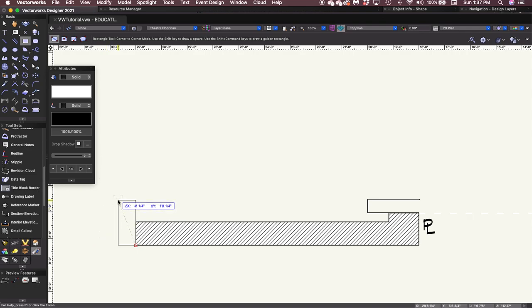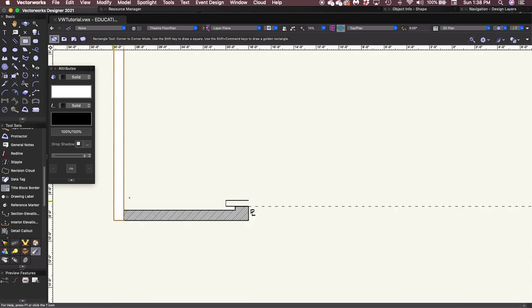So once again, we're going to tab into the floating display bar. We're going to make the delta X value minus 10.5, which is 10.5 inches. We'll tab over to delta Y, and we'll make it 26 feet. Great. And we'll click and establish our rectangle.